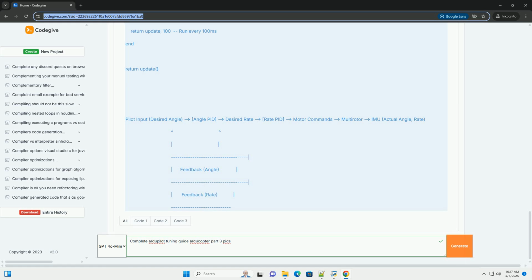4. Configure the specified RC channels in Mission Planner to correspond to switches or knobs on your transmitter. 5. The script will now allow you to adjust the PID gains in flight using your transmitter. This code associates certain RC channels to increase or decrease values for the PID loops.